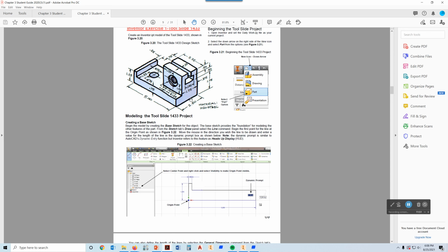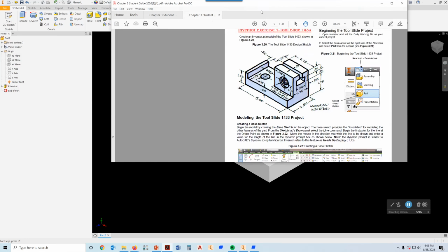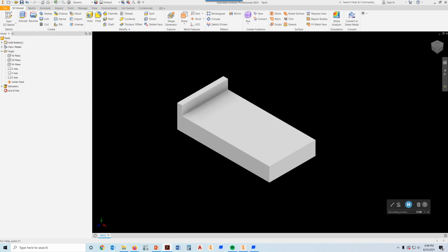But that would be if you're extruding from the very bottom. And since I'm starting right here at 0.75, and I know that if I add all this up, I get to 2.75, then all I need to do is extrude that 2. All right. So I'll show you how to do that, so don't worry if you're not exactly following what's going on here. All right, so what we want to do is start a new sketch on this surface right here.